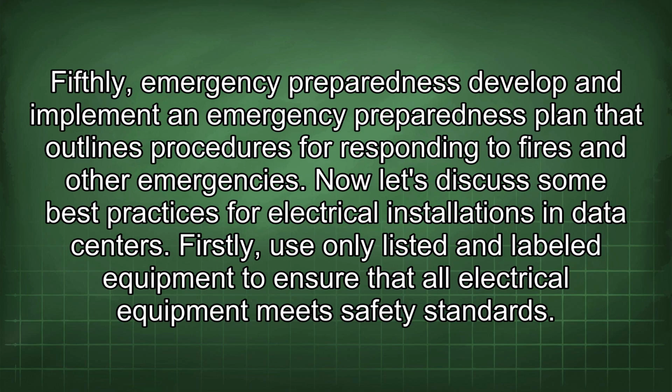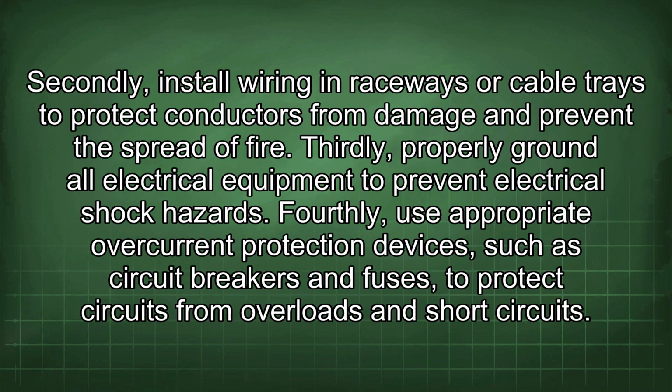Now let's discuss some best practices for electrical installations in data centers. Firstly, use only listed and labeled equipment to ensure that all electrical equipment meets safety standards. Secondly, install wiring in raceways or cable trays to protect conductors from damage and prevent the spread of fire. Thirdly, properly ground all electrical equipment to prevent electrical shock hazards.